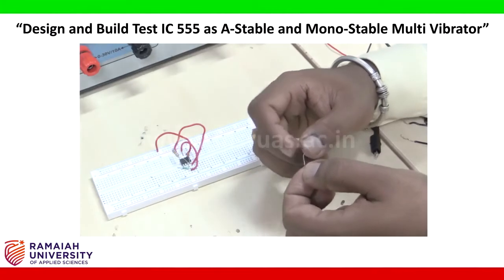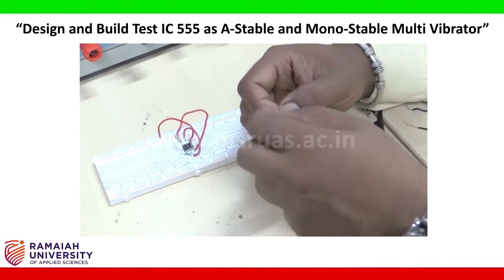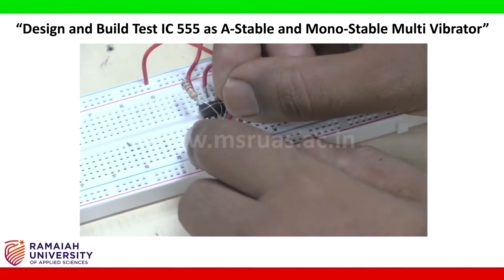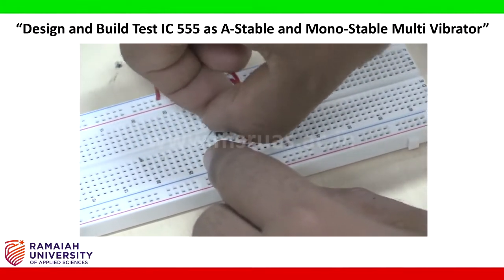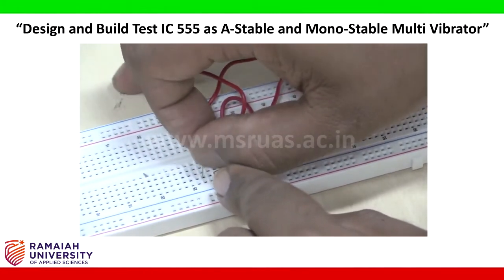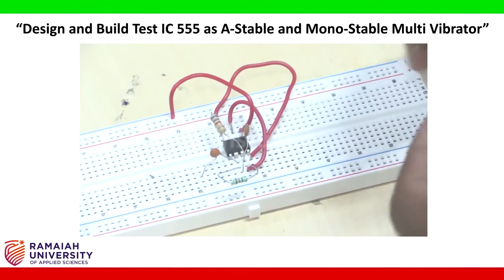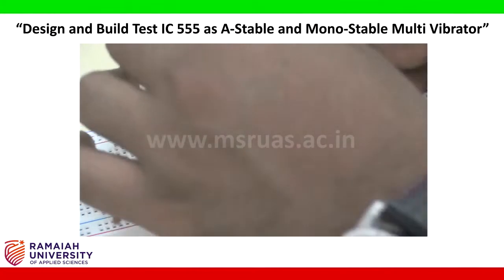Then I am going to connect the 0.1 microfarad capacitor to ground from terminal number 6. So this is terminal number 6. I connected this 6 to an external point in the circuit board, from here to here, and I am using another wire to connect it to ground. So this is the ground connection.